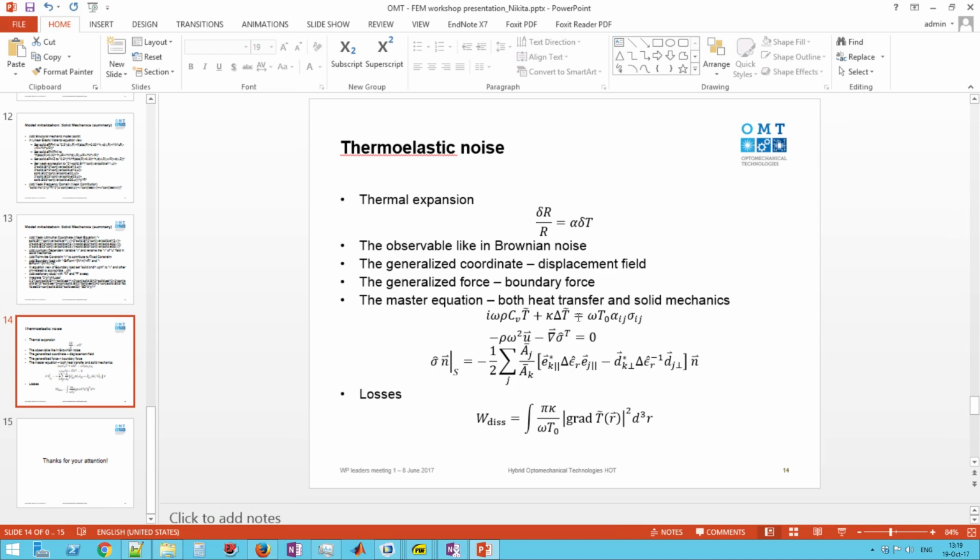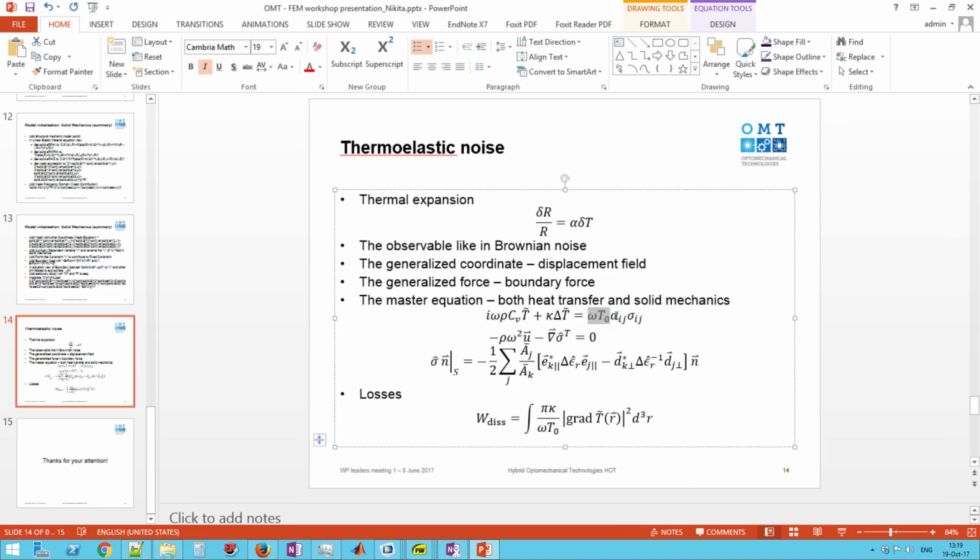So now we have the thermal damping, which is thermoelastic damping. Because the idea is to calculate thermal losses. If I calculate thermal noises, then the losses are thermal. If I calculate the Brownian noises, then the losses are Brownian, mechanical. So here I again use these equations for my mechanical part. Then the mechanical part is fed to the temperature part, and then I calculate the temperature losses.